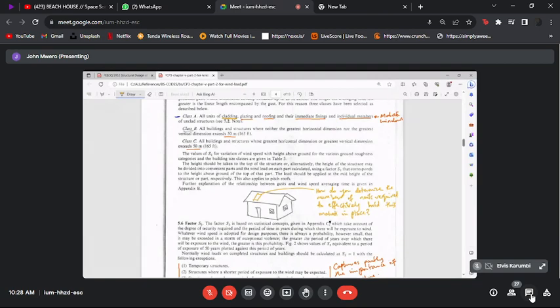Then that pressure is what would make the mabati piece fly away. The dimensions of the mabati piece, including the length that John mentioned, and the pressure give us a force. Then we would ask, one nail, how much force can it hold? Then we say, so we need to put this number of nails to hold the mabati.